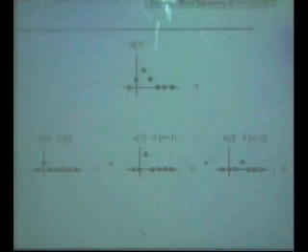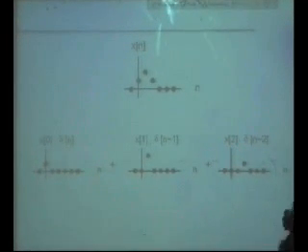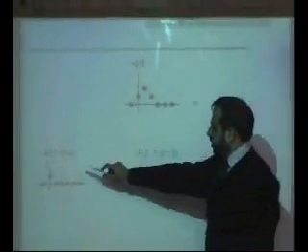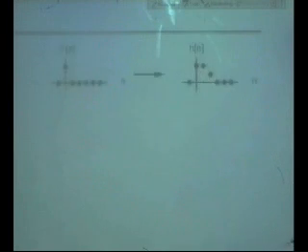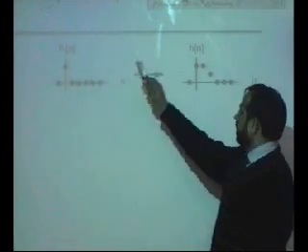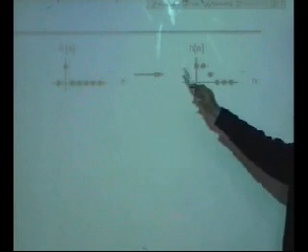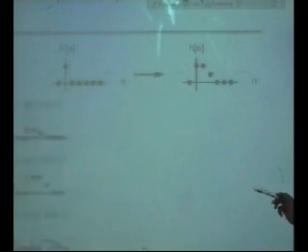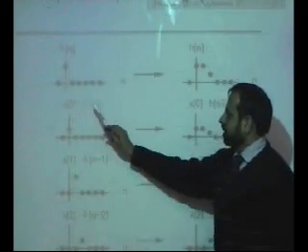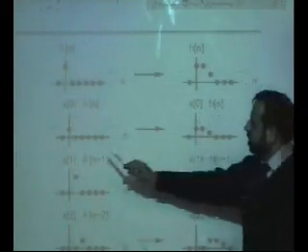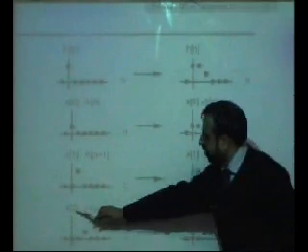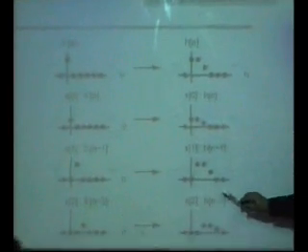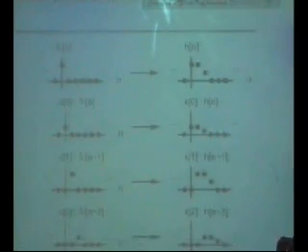And this is how we interpret this: a signal is disintegrated into weighted shifted impulses. For delta of n, the output is an impulse response. Then for a weighted shifted impulse, you get a weighted shifted impulse response, and so on, and add them together.